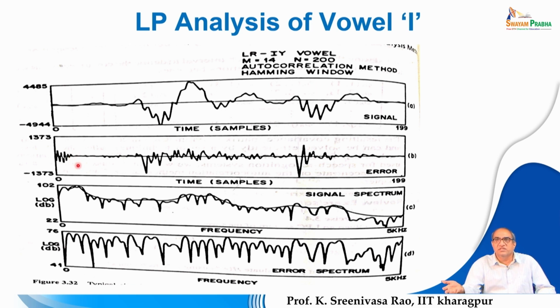Residual means the remaining, that means whichever part is not captured, not predicted. The remaining part of the speech signal which is not predicted is the linear prediction residual. That is the reason that, when you are designing the generative filter, the signal that remains from the prediction is used as the input to the generative filter, so that you can get a proper speech outcome.